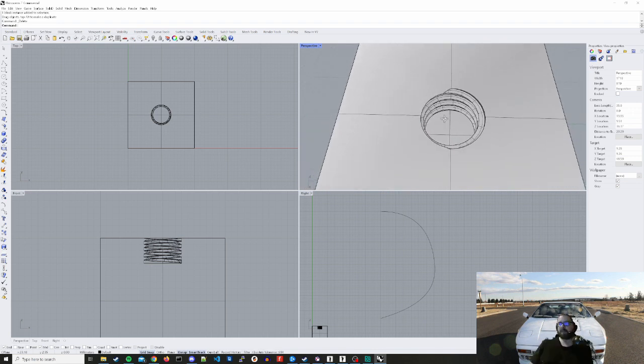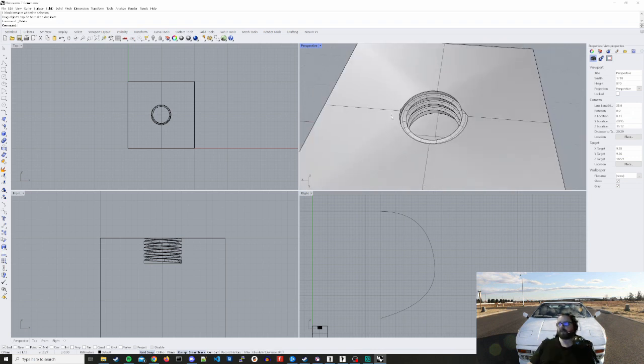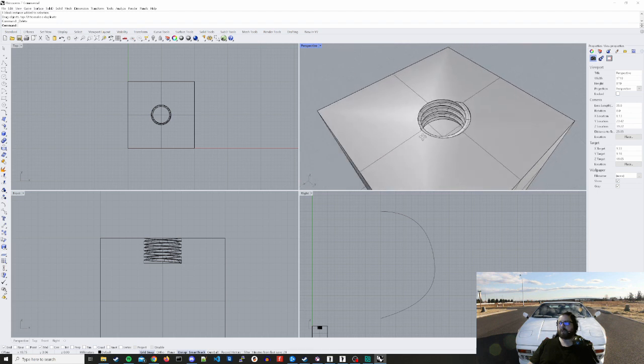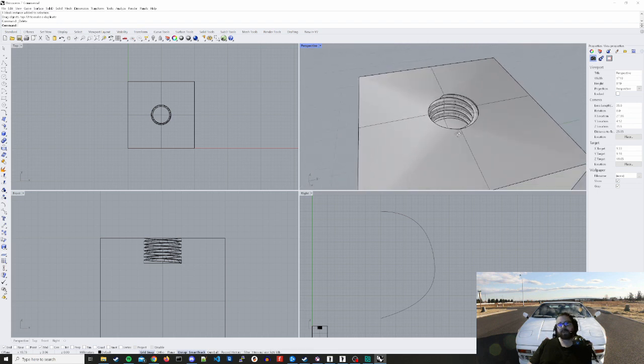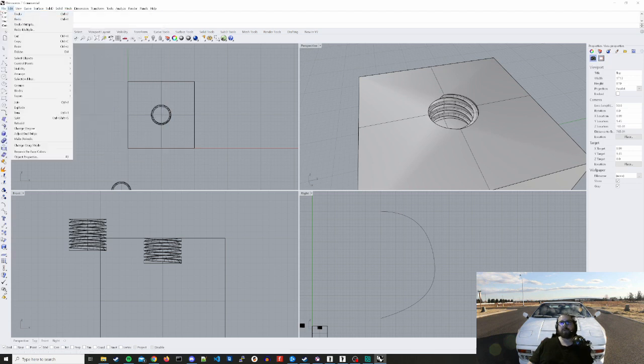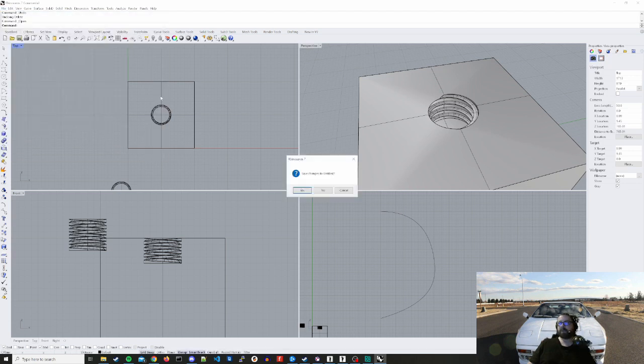This is kind of nice because you can get other fasteners. You can print threads in here. You do not have to print threads with support material 99% of the time. So for those of you who are looking at this with an engineering aspect, like, hey, I want to make some functional stuff for my cars, or maybe I want to make something that can be bolted in, here you go. It's as easy as this. Now converting those files over, what you would do is you would open the file itself.